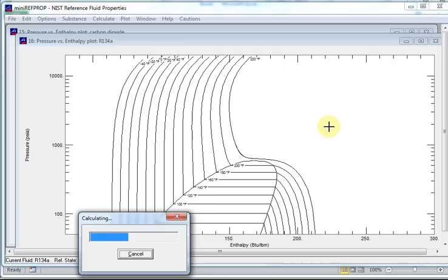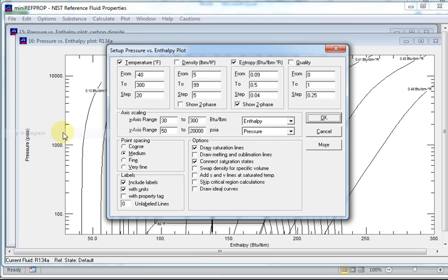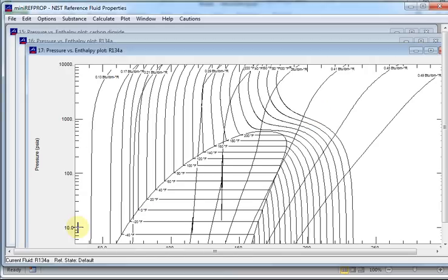Boom. Okay, so if I wanted to absorb at this temperature, I've got to go a lot lower on my pressure. Let me replot that. Pressure enthalpy. Where's my pressure? X is right here. I've got to go down to, I don't know, 5 psi. And there's no sense going up that high. Let's do 10,000. All right. There's 10. That's negative 40. So here's negative 20. Here's 0. So there we go, right?